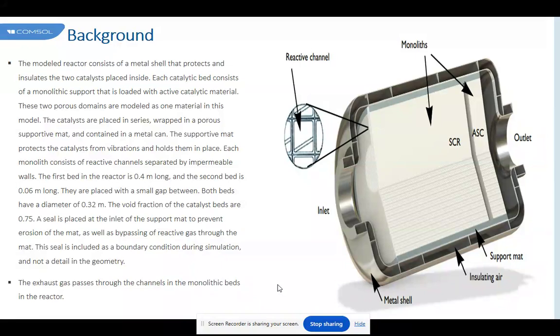While high substrate conductivity leads to superior steady-state performance, it may lead to a longer transient time. Thus, the effect of the substrate material on the overall performance of a monolith is not clear. There are few studies, mostly experimental, in the literature comparing the performance of ceramic and metallic monoliths. We review here briefly the literature related to this topic.